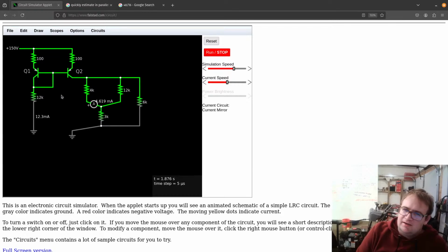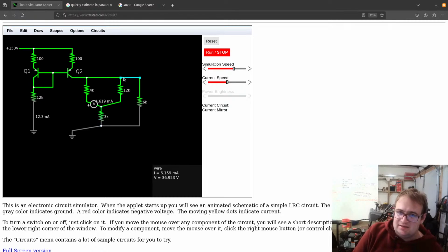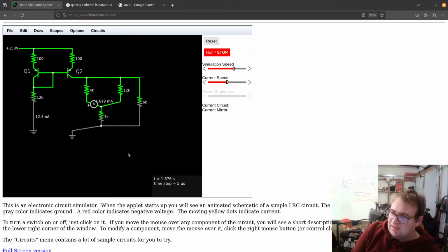I don't know where I had got that trick. Sometimes I do some weird things inside my head. But yeah, so this is 3 kilo ohms there. So that means that's 6 kilo ohms here. So that means that the overall resistance will be 3 kilo ohms. If you have 12 milliamps times 3 kilo ohms, that means 36 volts.